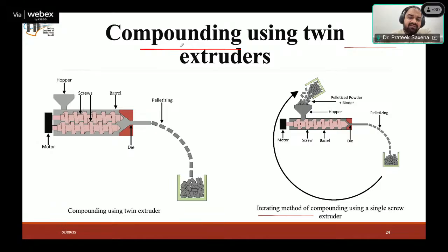So when a filament is being formed for the first time, it might be possible that all your metal powders come together in one particular zone. Then in the next zone there is no metal powder at all, and then in the third zone the metal powder is again present in a very specific zone. Now the problem with this is that the metal powder is non-homogeneously distributed, which I don't want, because later on I'm going to use the same filament for 3D printing my part.